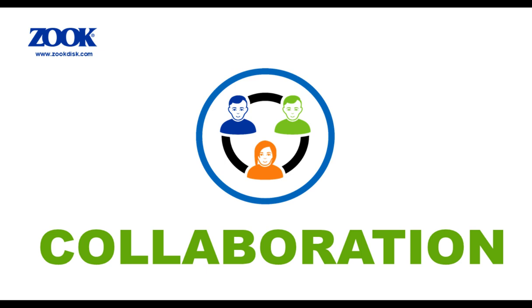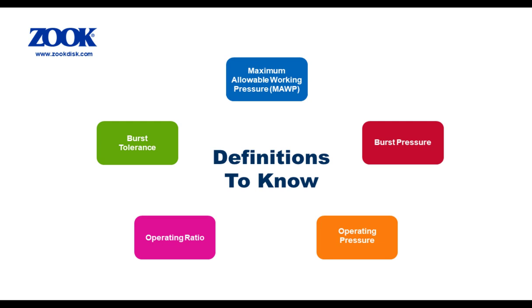As you can see, selecting the best possible rupture disc design is not a simple task for any one person to tackle on their own. Good collaboration between the end user, system designer, and disc manufacturer is essential in getting it right the first time. Every application has both common and unique criteria that will guide the selection process. Common criteria include the following: vessel maximum allowable working pressure, otherwise known as MAWP, disc burst pressure and temperature, normal system operating pressure, operating ratio, burst tolerance.